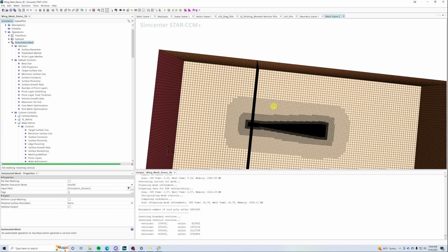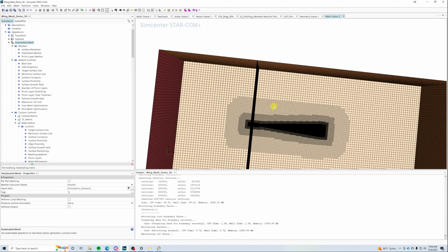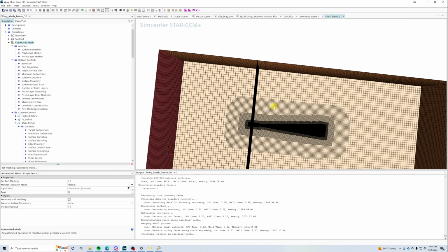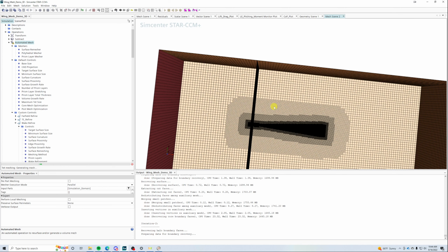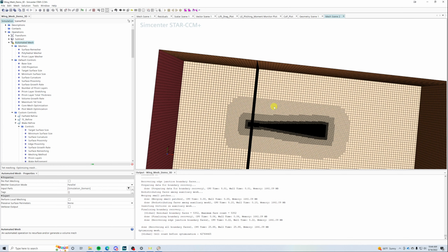So if you have like a complex pipe, for example, maybe a trimmer mesh isn't the thing. Maybe a polyhedral mesh is the thing you want. Or there are other meshes that can sort of give you the efficiency of a trimmer cell mesh, these cubic cells, but it will do it in a curved manner. It will curve cuboids in such a way that you still retain the efficiency of a trimmed mesh, but instead get the ability to conform to complex curves closer to what a polyhedral mesh does.